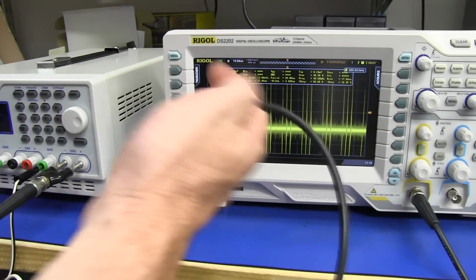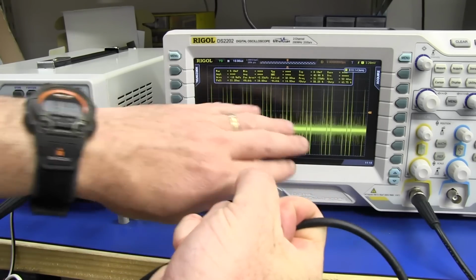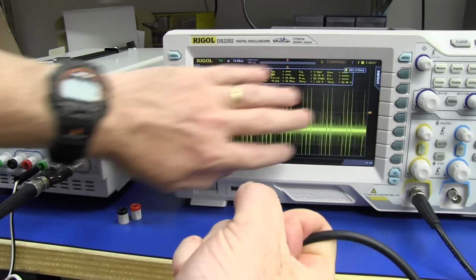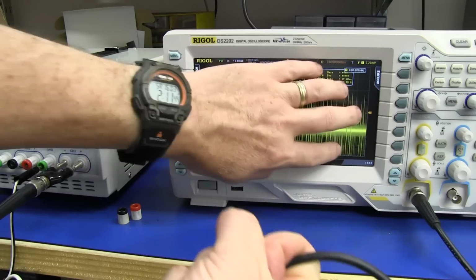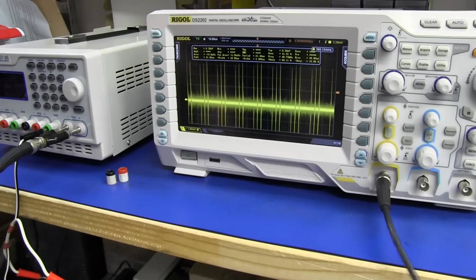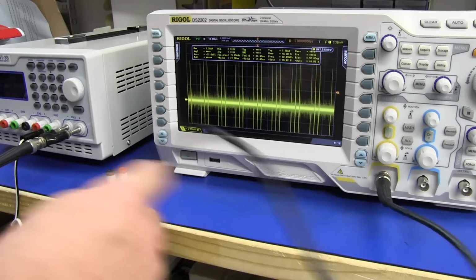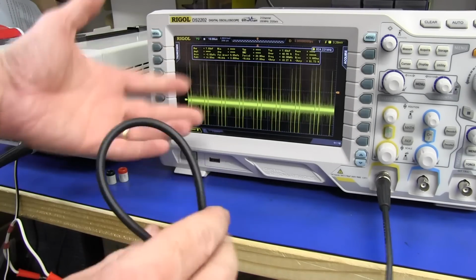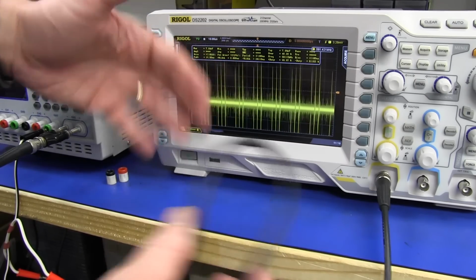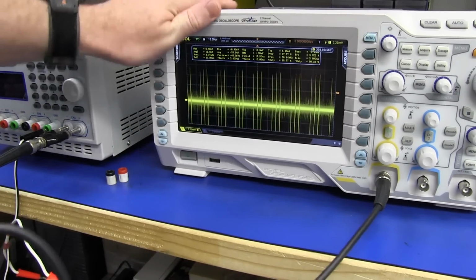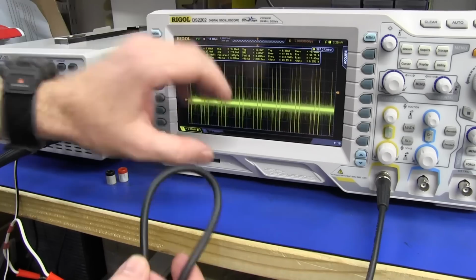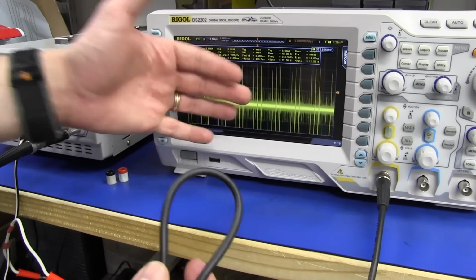Be careful, watch this. I'm going to grab this coax with one hand, touch this screen over here. No, folks, it ain't magic. It's picking up the noise, the switching, that refresh of the screen there. Look at that. Woohoo! And of course, that is one of the disadvantages of these digital scopes, that they can be spewing out stuff which can interfere with low value measurements. So that's why a lot of the greybeards frown upon these digital scopes, because they can be generating all sorts of crap. You won't get this sort of thing happening with an analog scope.